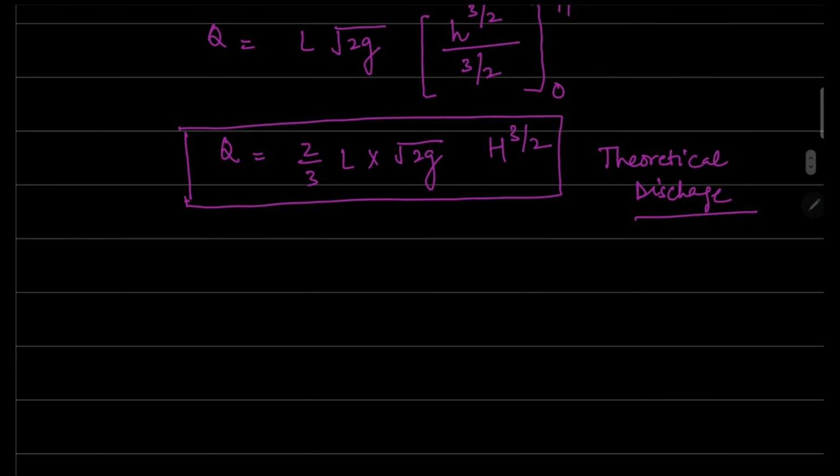So with the involvement of the channel and some very sharp opening, the theoretical discharge we are getting will not be the actual discharge we will measure in the actual condition. So in order to assess the actual discharge, we have a coefficient that is called CD.